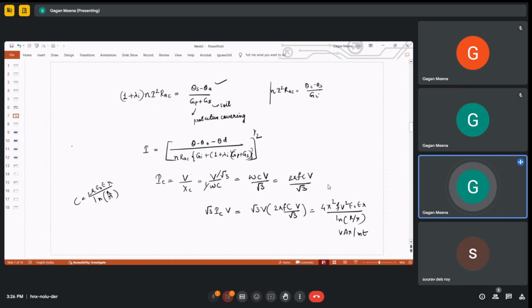And this flow of charging current causes heating in the cable, and therefore the load current capability of the cable is decreased. After discussing this, we entered into transient overvoltage.